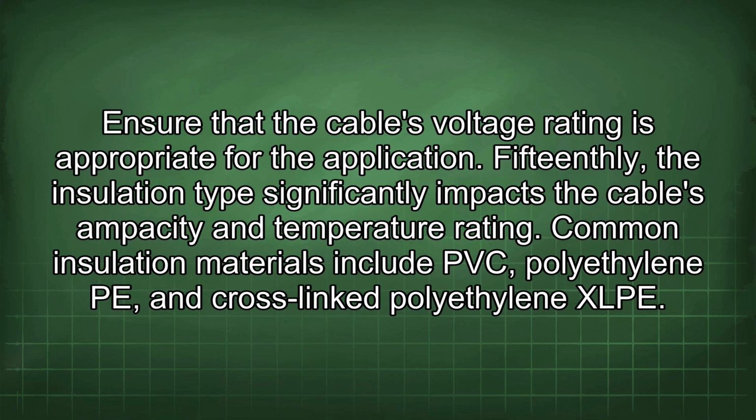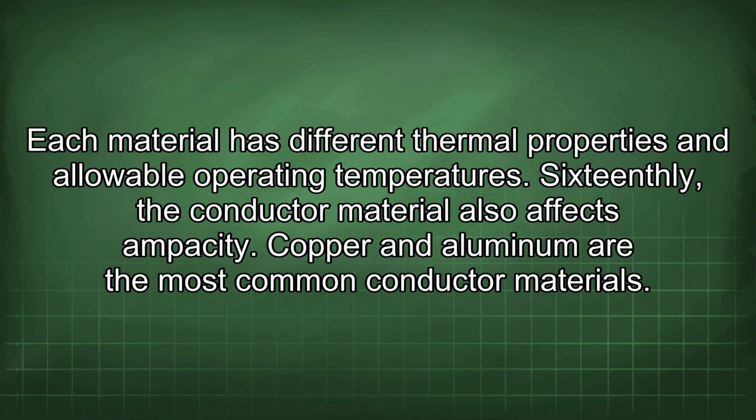15thly, the insulation type significantly impacts the cable's ampacity and temperature rating. Common insulation materials include PVC, polyethylene (PE), and cross-linked polyethylene (XLPE). Each material has different thermal properties and allowable operating temperatures.